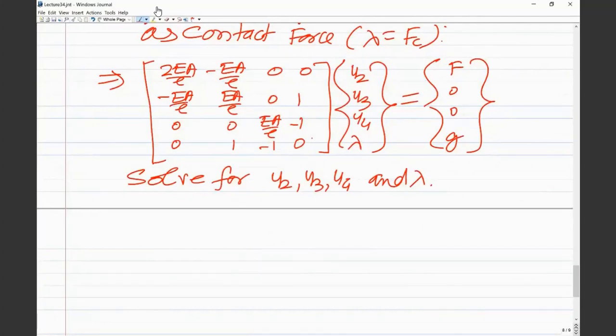The other one, no, there is another method also. You can actually use the penalty method. So in this Lagrange multiplier method, number of unknowns has increased by 1. That is, Lagrange multiplier itself is an unknown variable. So number of unknowns are increasing. So if there are more constraints, there will be more number of Lagrange multipliers. So we have another method known as the penalty method.